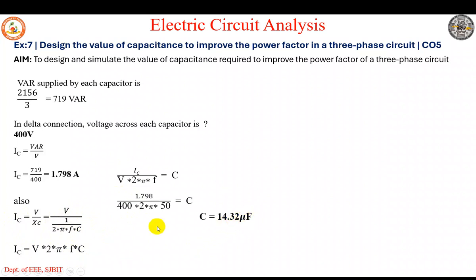However, for a single phase, when you solve this problem, it's a balanced circuit. In theory class, you'll understand the difference between balanced and unbalanced circuit; I'll restrict my explanation with respect to this experiment. Under a balanced circuit, we can solve the entire three-phase problem as a single phase.